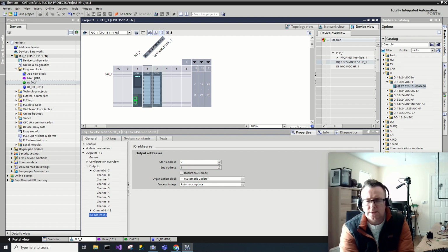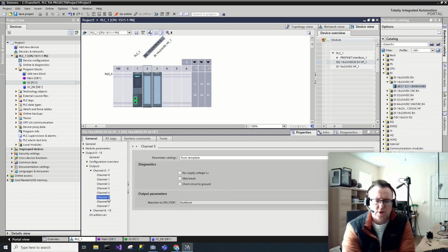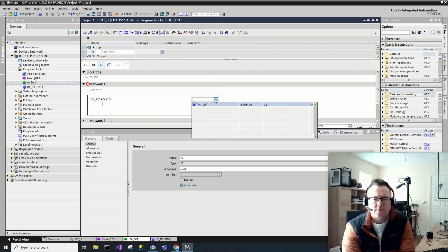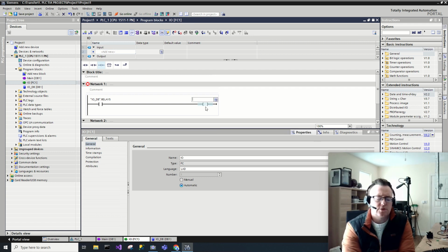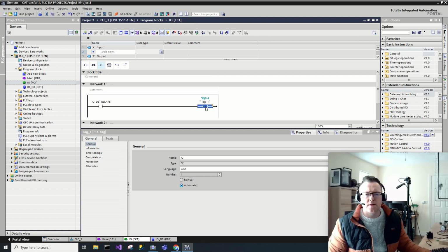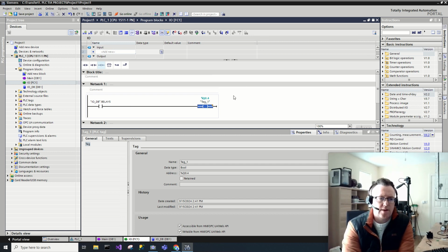Okay, so in order to get channel number 5, it's going to have to be 0.4. That's basically it. So this is pretty much what we're looking for here. Let's go back, and we're going to go on the output, and it's going to be down as Q 0.4. There we go. So it's an output, and that's there.